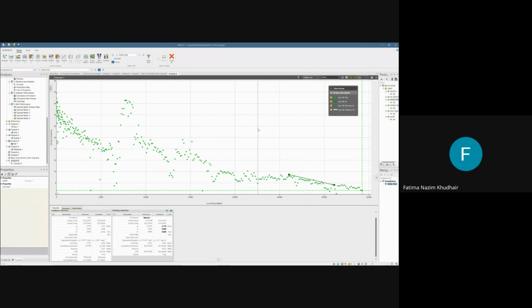There's a lot of tools used in OFM to clean up your data. For example, you can right-click and use the lasso to exclude points. If I see that these points are affecting my forecasting, I can remove them. Okay, they are fading now. So these points will not affect my forecasting. Also here, just like outliers, just by drawing a circle, okay, now it's faded.